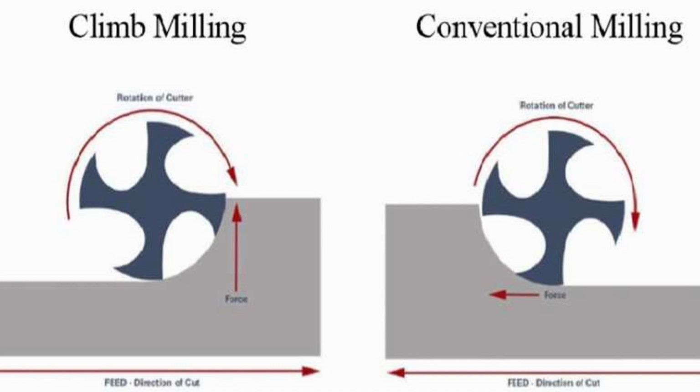Climb is usually a better chip remover, and so you can go faster when using the climbing cut. However, conventional cut can give you a better finish, but normally with only very, very small material being removed. If you're removing a lot of material, the conventional cut doesn't remove chips as well, and so it can drastically affect your chip load and can slow things down.